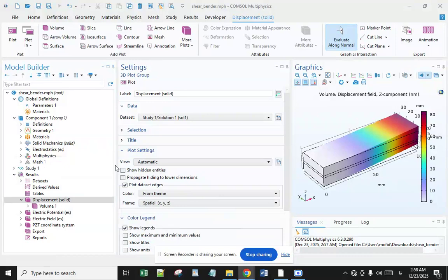This simulation presents the formulation and validation of a new adaptive sandwich beam finite element capable of dealing with either extension or shear actuation mechanisms. This is achieved by coating an elastic core with piezoelectric sheets or sandwiching a piezoelectric core between two elastic faces. The poling direction is taken parallel to the transversely applied electric field for the first mechanism and in the axial direction for the second one.